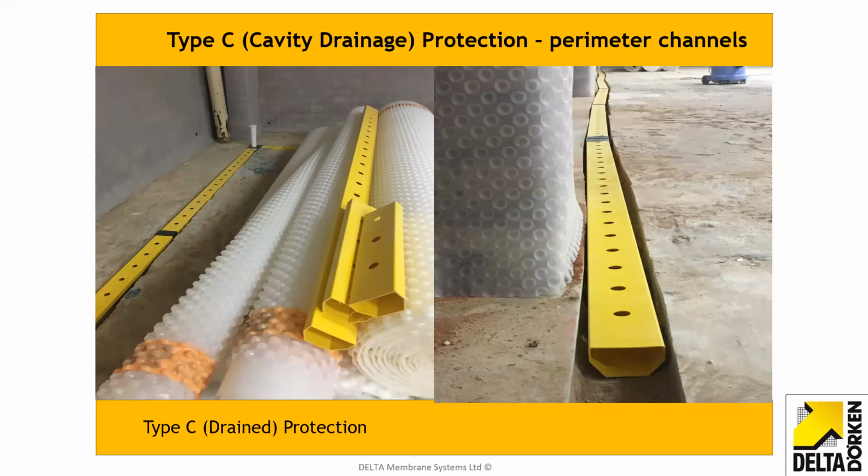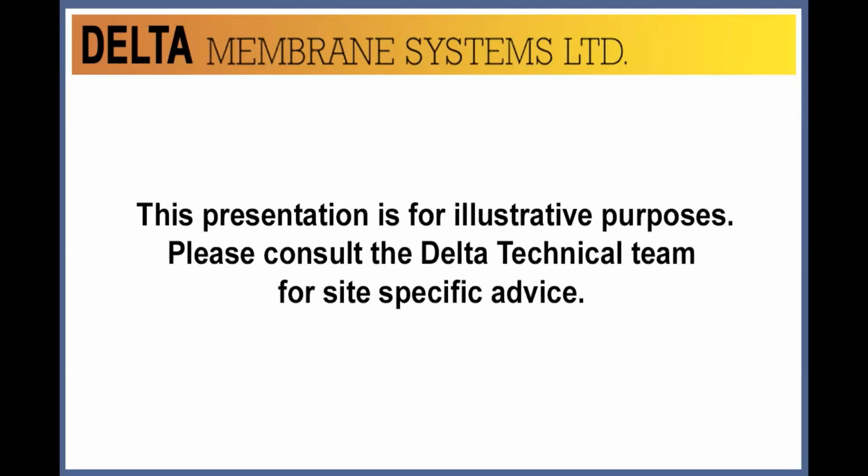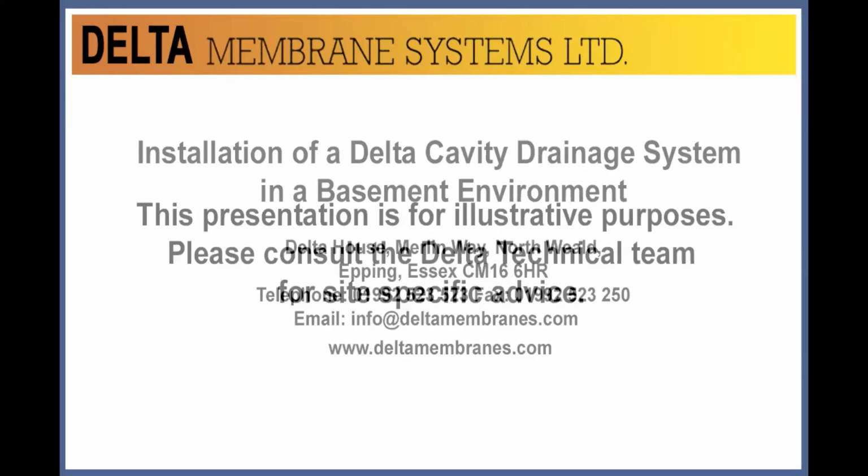It's a maintainable system, passive system, doesn't block water out, isn't under pressure, doesn't need perfect workmanship to work, needs a good standard of workmanship to work, but not perfect. So it's a forgiving system, and it's a great system as an insurance policy to back up other systems. This is just a quick illustration of a cavity.